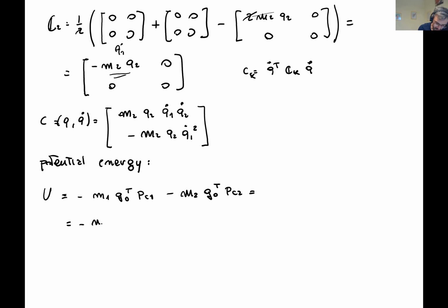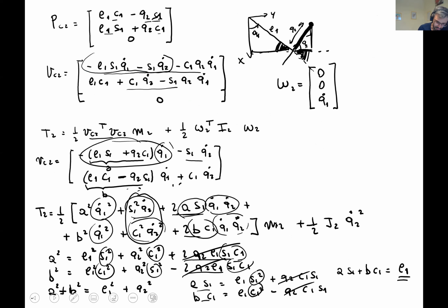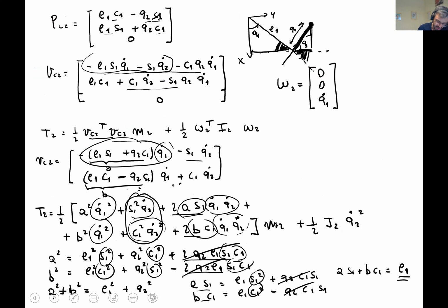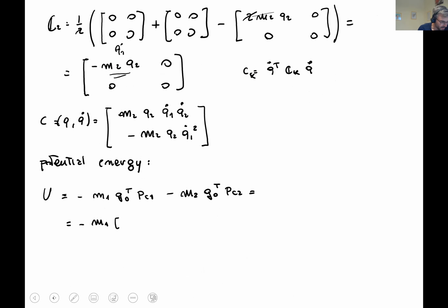And now there is a trick here. You need to be very careful, because if you look at the way we defined the reference frame, I did it on purpose, now it is pointing down. So the G vector does not have the Z component with the G value, 9.81, but the X component. So you get minus G, 9.81, along the X component, 0 and 0. This is a row vector because you do the transpose, and we get the expression for P1.